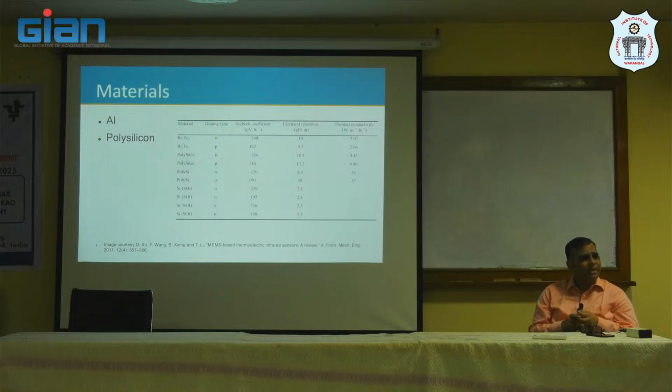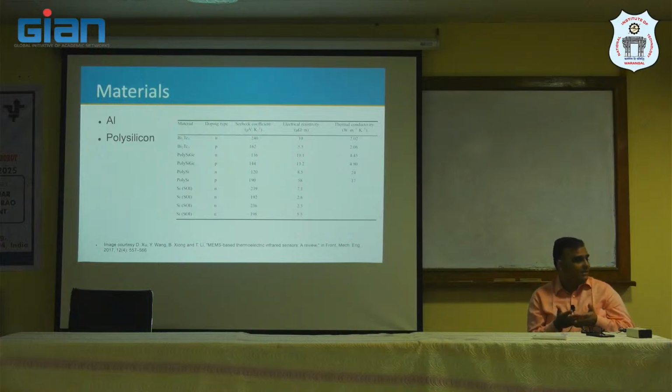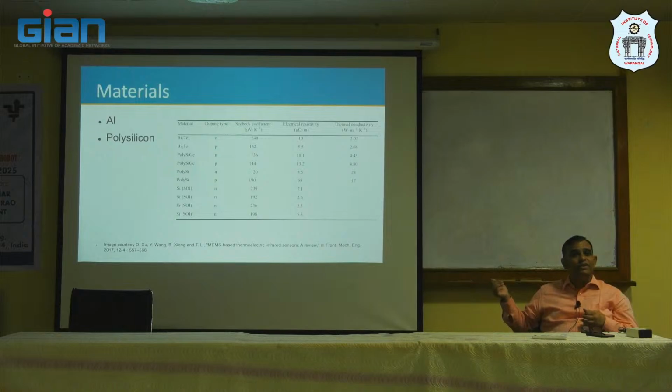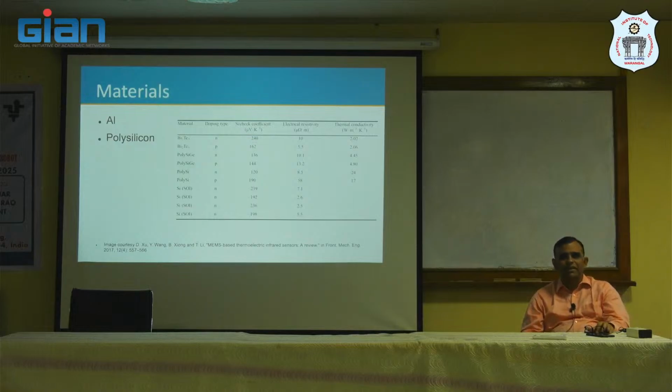And it's available. We made the transistor using polysilicon. So, I don't need to introduce a new material in my process. Other things like bismuth telluride, which are on top, are not inherently available in a silicon process. Right? Even silicon on insulator means I have an insulator base, then a dielectric, and then silicon. It's a costly process to make. So, people used to make chips on things like silicon on sapphire or silicon on diamond,